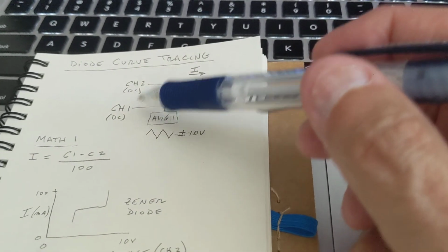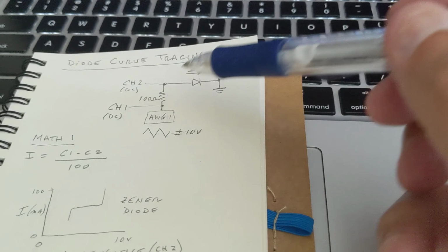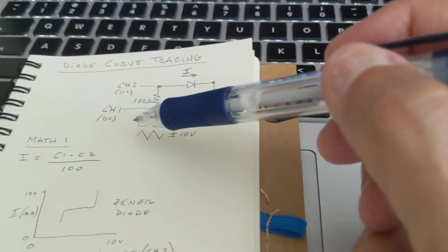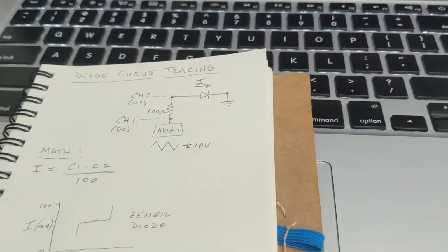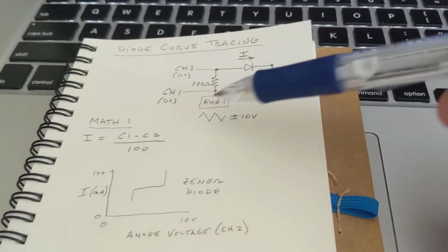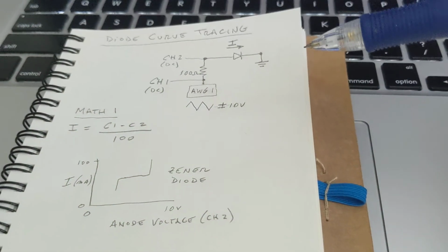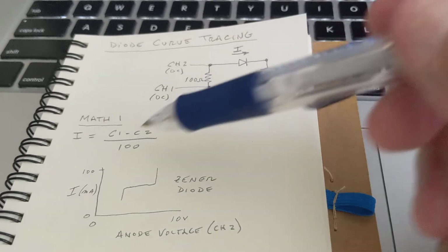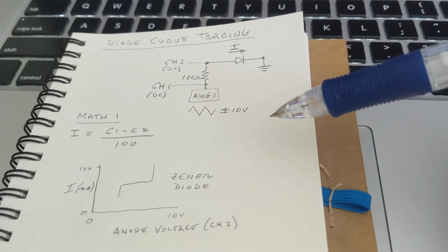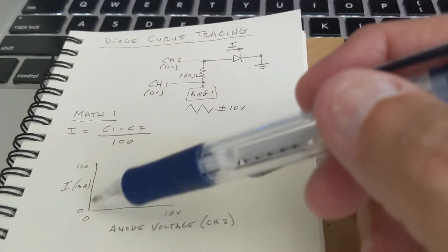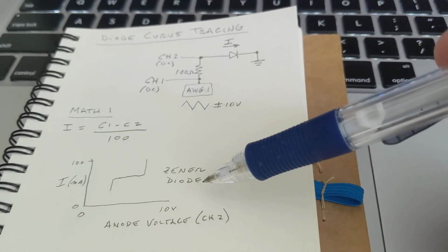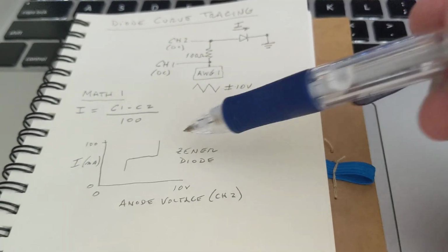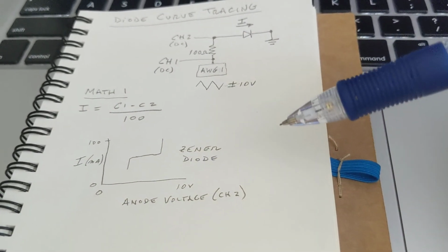We're measuring the voltage on either side of that resistor with channel 1 and channel 2, the DC inputs on the Electronic Explorer board. We then apply Ohm's law in a math channel in waveform software to calculate that current flow. And then we plot the results, current flow versus voltage across the diode, and we end up with this XY plot that you see on the screen.